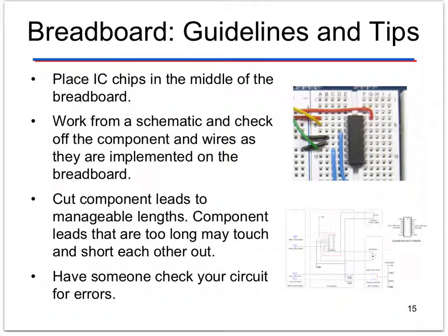You need to place IC chips in the middle of the breadboard. You'll see there's a little slot down the middle there. Your IC chips should straddle that slot. Work from a schematic and check off the components and wires as they are implemented on the breadboard. So as you complete the breadboard, check off stuff on your schematic.